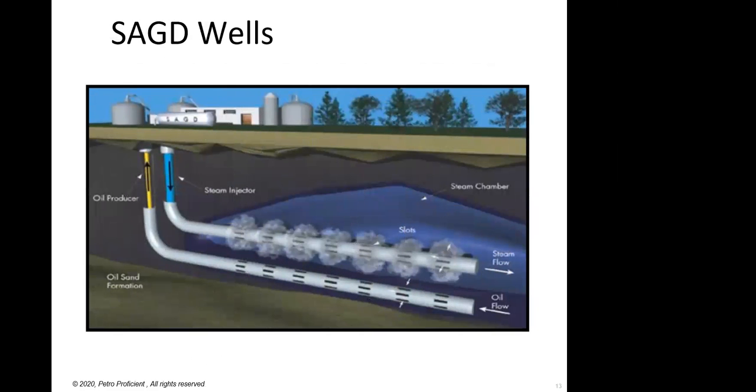The other type of application of directional wells is SAGD wells. You may or may not have heard of this, but it is an enhanced oil recovery technique called SAGD, which is steam assisted gravity drainage. It's a part of enhanced oil recovery technology, and where you have heavy oil and bitumen, this form of wells